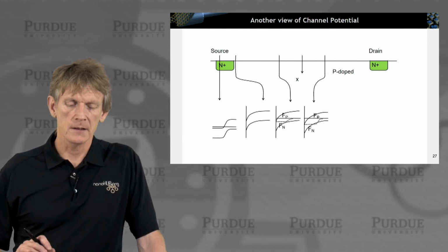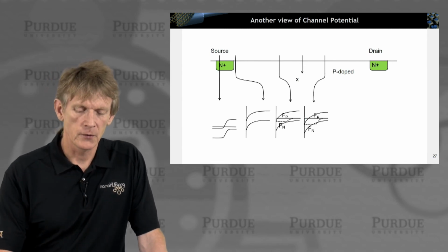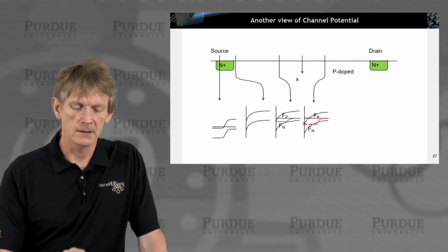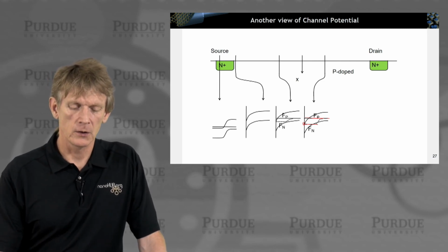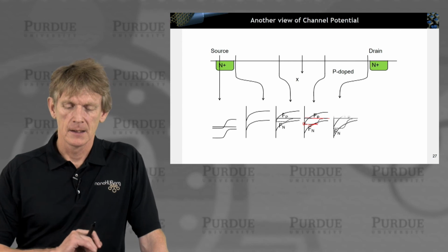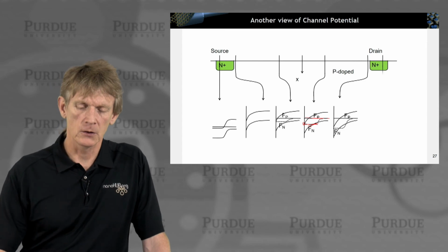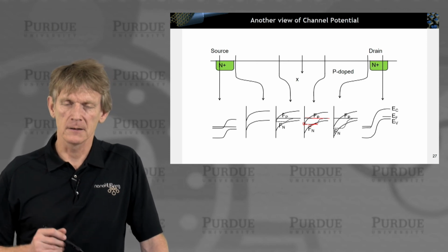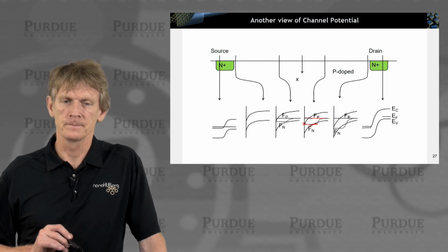If you're much further away, you're driving the system harder, where you have the Fermi level way up here for the holes, and the electron stays pegged here, and the electron channel gets a little narrower, but you will have an effect on the exposed acceptors. And here you're separating more and more the Fermi level for the electrons and for the holes as you go down the channel. And if you're far away again from the channel, and if you're just looking down under the drain, it looks like a normal p-n junction again. Okay?